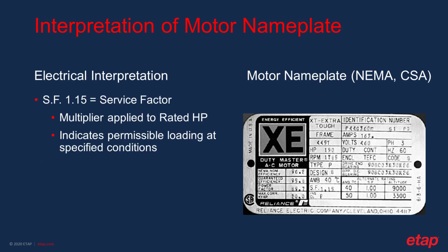Service factor is also another important parameter in overload protection, especially in motors which are made based on NEMA or CSA standard. Typically the IEC motors have a service factor of 1. This multiplication factor is applied to the rated horsepower, meaning it will be applied to the full load current of the motor too. So for overload protection, you need to be aware of this service factor and naturally permit the overloading of the motor based on service factor and adjust your overload protective devices accordingly.